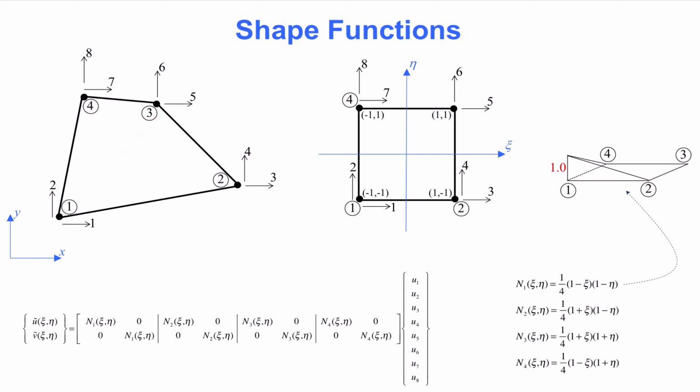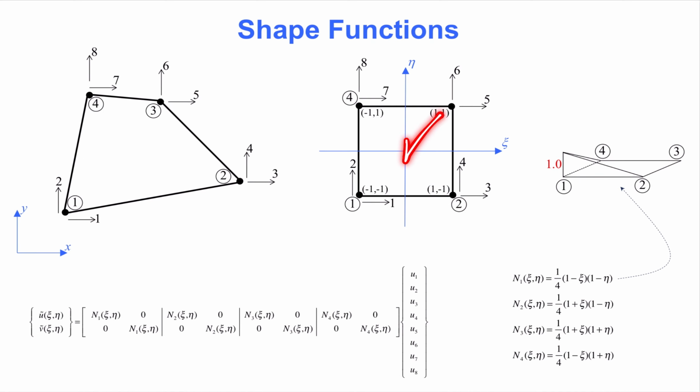This is why we will formulate the shape functions for a square template element in the eta coordinate system. The element spans from -1 to 1 along both axes. This template element will be transformed into actual elements of any shape. A shape function in the finite element method has the following characteristics.